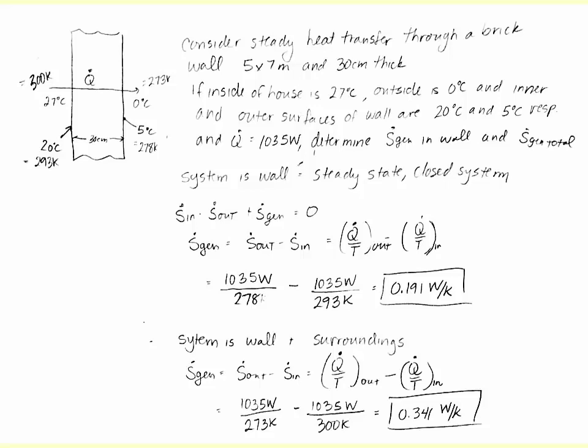Yes. How? Inside heat. Okay, by a heat transfer, right? So there's heat transferred into the system. We will have entropy in. Is there heat being transferred out of the system? Yes. So we'll have an entropy out. And then entropy generation is just a byproduct of an irreversible process. This is not a reversible process, so we'll have entropy generation as well.